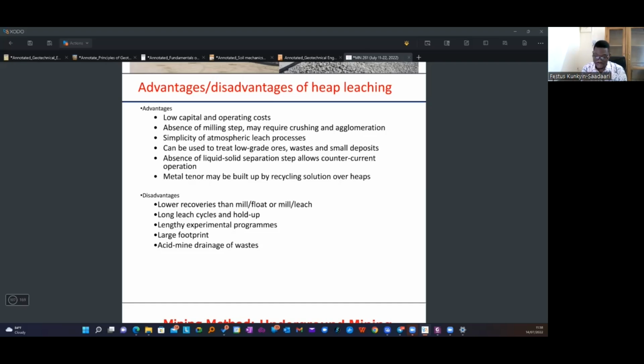And in other cases, if you intend to undertake leaching, then it means that your drill patterns, when they are doing the drilling, you have to inform your blast engineers to make the bedding and the spacing, which we explained. The bedding and spacing should be close enough so that when you blast, you get smaller size materials that you could use for your purpose.